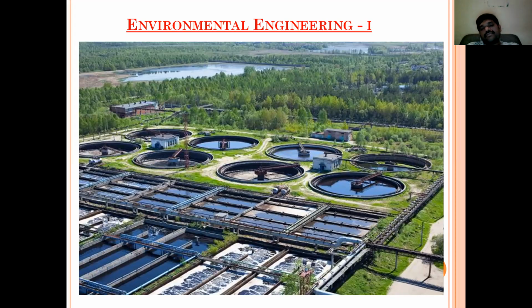And also, there should be proper planning, and the water must enter into the next unit based on gravity. The elevation must be such that water will enter into the next zone by gravity, not by pumping. We have seen staff quarters must be there, and a clean atmosphere has to be maintained in and around the treatment plants.